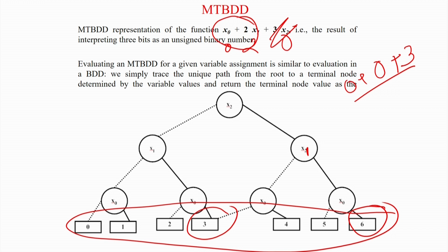So when people moved away from BDD to abstract level, they started something called a multi-level BDD. The philosophy will remain the same: they will take a binary decision tree and start applying the philosophy of redundancy elimination in a slightly roundabout manner, not as simple as we can do it in BDD. For multi-terminal BDD, the elimination of redundant nodes etc. is slightly non-straightforward. I will put up the references on the web, if you want to see. But basically the idea is similar.